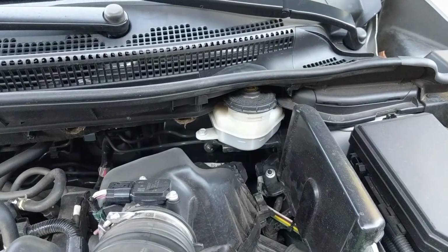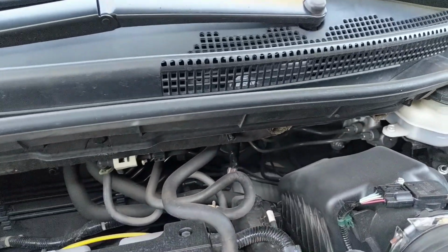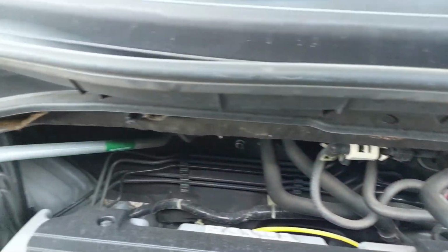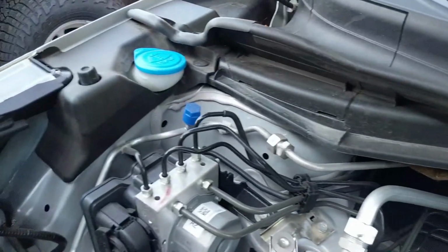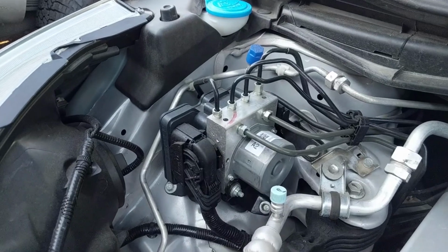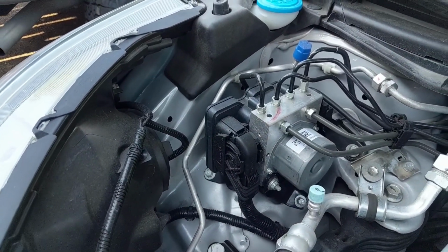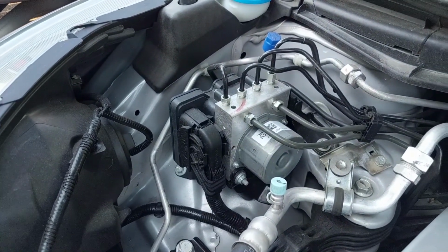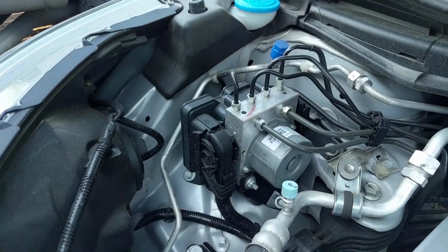Follows the same pattern. So maybe you recognize this setup. This is the one with the master cylinder reservoir that's hard to reach, and an even harder to reach master cylinder. Well, those lines, if you recall, see them running around the firewall there, come around to the hydraulic control unit. This is not an integrated system. This hydraulic unit and the module are separate from the master cylinder assembly. So it's not completely integrated, but these two components are usually coupled together.